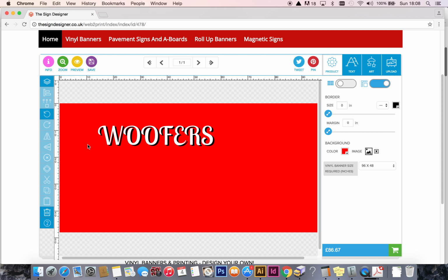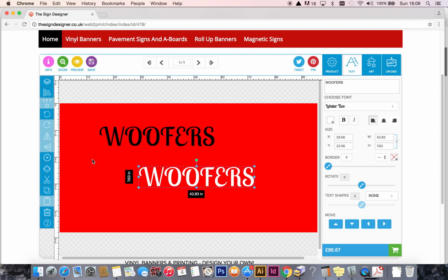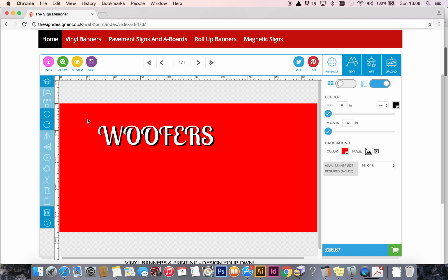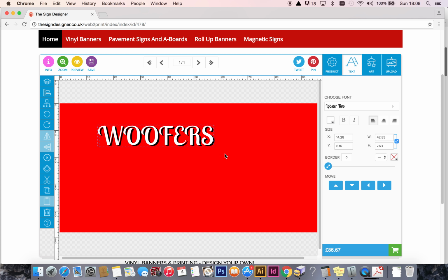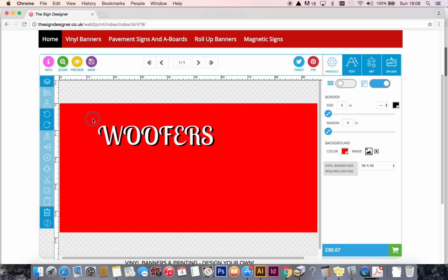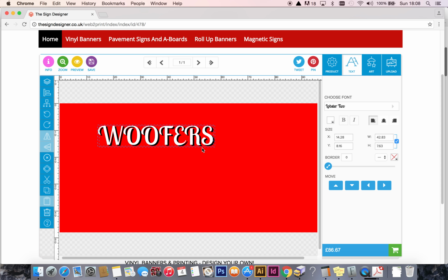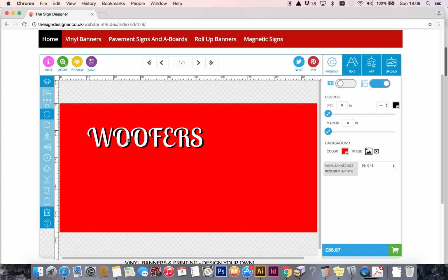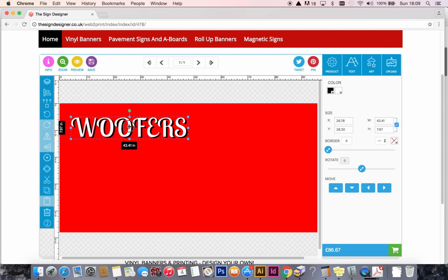The next thing I need to do is stop this moving around independently, which we don't want. I'm going to use the undo tool now, by the way. There's another tool, undo. So undo and undo. To stop them being moved around, I am going to rubber band the both of them. Now rubber band means click, drag and let go. Okay, let's do that again. Rubber band, click, drag and let go, and you'll see that both of the items have a broken line around them. Okay, that means they are selected, so now I can group there, and now both of the items become one. You see, now I can move them around and they don't become separated.